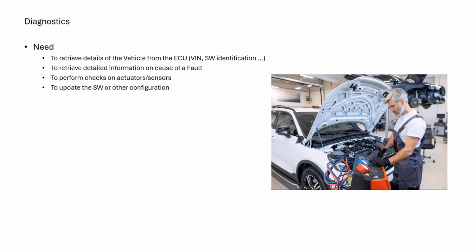If you want the latest software updated to a particular ECU, or you want to flash some configuration related things, for that we need diagnostics. It's also needed for component checks at the service station through routines and tests. Routines are one of the UDS services. We'll be discussing all UDS services in further sessions. Many UDS services are there which are useful for our diagnostics.